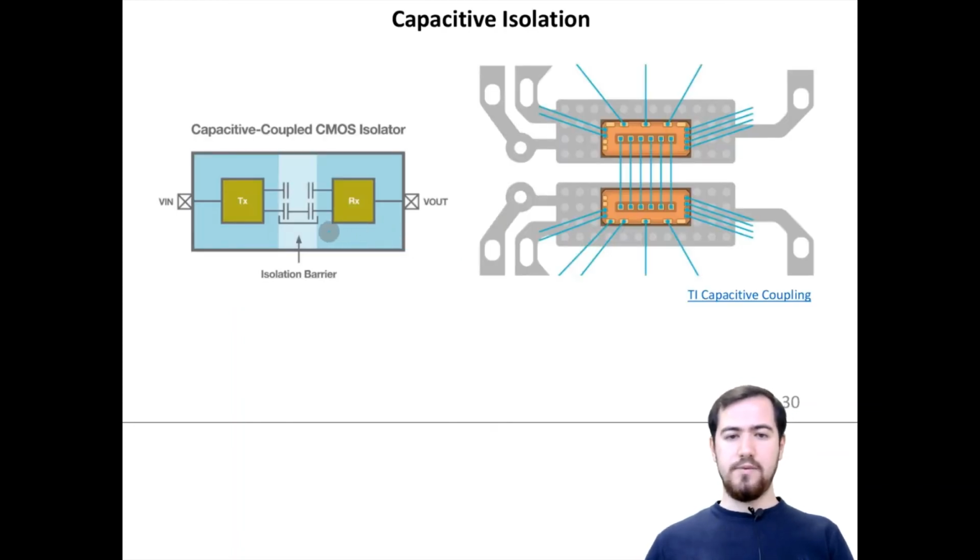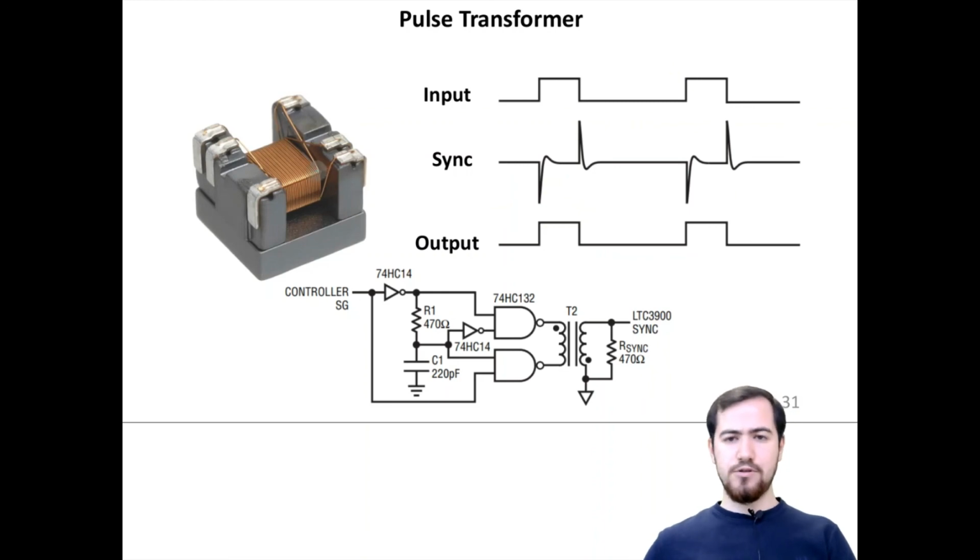Another method, as we said, is the capacitive isolation. The DC current cannot go through the isolation barrier. However, the AC signal can be transferred. Let me write here: it is DC and this is AC through the capacitive barriers. And this is the configuration of its die. The capacitors are here, connected in a vertical way. This is the isolation barrier between the two sides, and we need to pay some attention to these isolation requirements. But first let me show another type of isolation component.